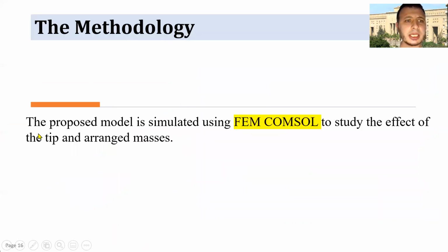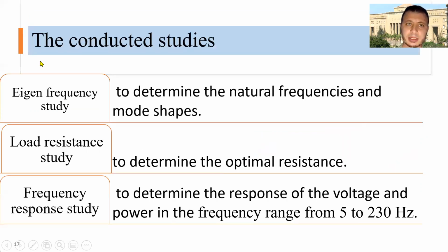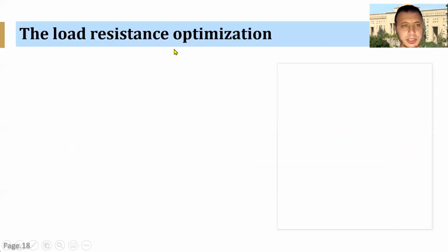Results and discussion. The methodology: the proposed model is simulated using finite element COMSOL to study the effect of the tip and arranged masses. The conducted studies: Eigenfrequency study to determine the natural frequencies and mode shapes. Load resistance study to determine the optimal resistance. Frequency response study to determine the response of the voltage and the power in the frequency range from 5 to 230 Hertz.